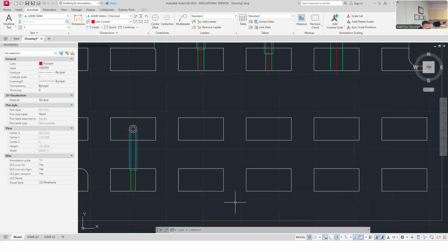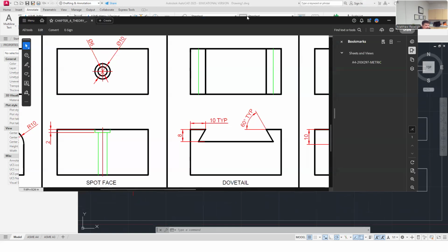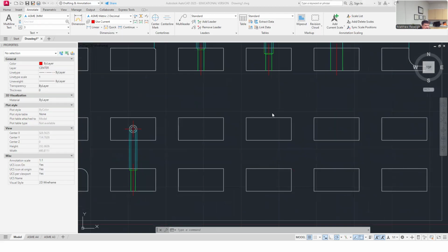Yeah. Anyway, side note, let's draw a dovetail. I've got my drawing up. Let me put it in. I think I'll start it from the front view. That tells me that it comes up, so I'll be on my visible line layer.